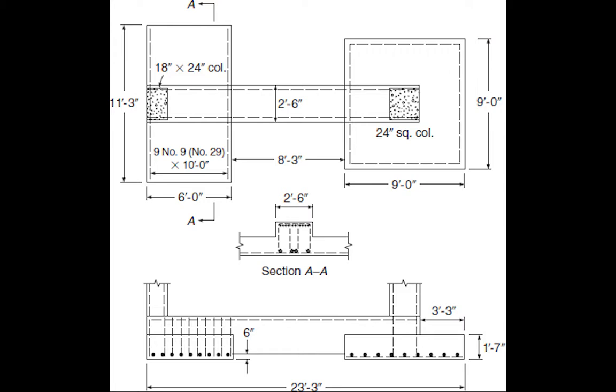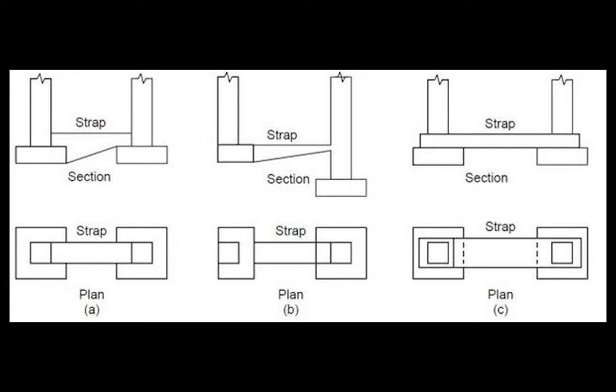The strap beam doesn't remain in contact with soil and thus doesn't transfer any pressure to the soil. The strap, assumed to be infinitely stiff, serves to transfer the column loads on the soil with equal and uniform soil pressure under both footings.